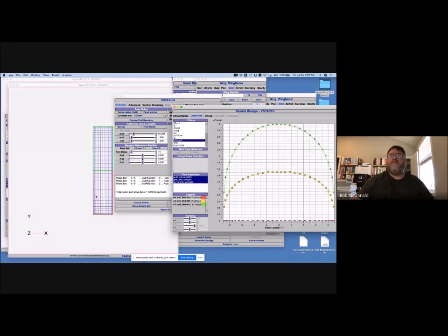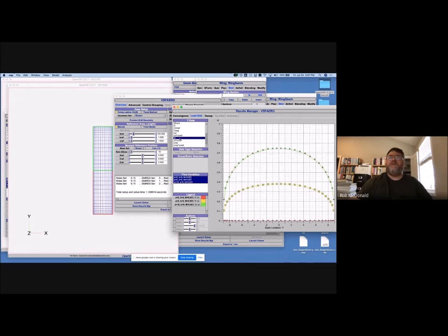So this is a Hershey bar wing, and notice this is its lift distribution, but when we look at the sectional CL, see it looks much more rounded. It's high in the middle. And so this wing, when it stalls, it's going to stall in the middle of the wing. So you're going to lose that lift in the middle, which doesn't have that moment arm. And so when you stall this Hershey bar wing, this rectangular wing, it's going to feel very mushy, right? You're going to lose lift and you're going to go into that stall, but it's not going to cause a big rolling moment.